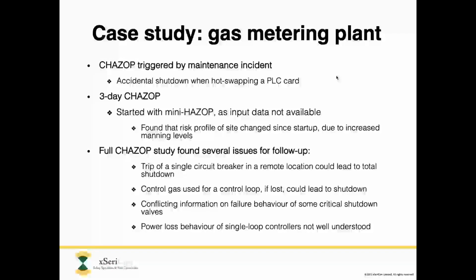So maybe the software crashes, or maybe it gives a ridiculous result, like a negative number or something, which the I/O cards then interpret as zero and send the zero, for example, zero position to a control valve, or command a shutdown valve to close, something like that. So that would be the cause. And then we would identify the consequence by looking at all of those fail low cases that we identified in the HAZOP study. And that will tell us what is the reasonable worst case consequence. And from that we should actually be able to tell whether a software criticality analysis is appropriate.